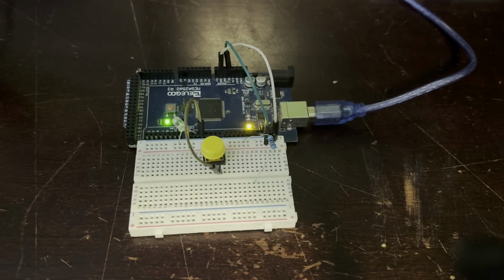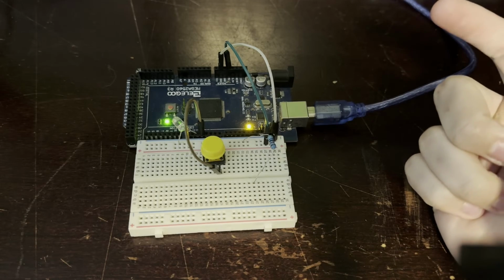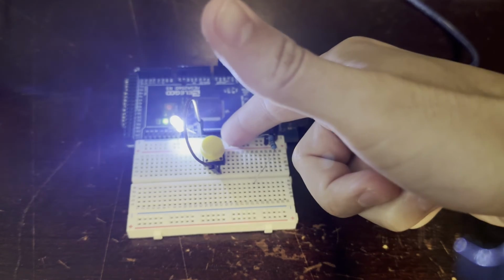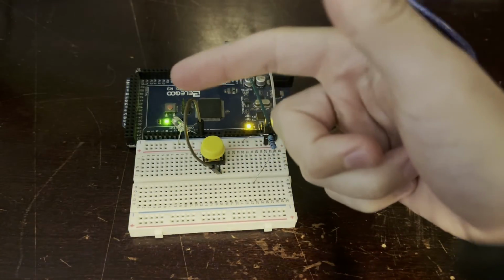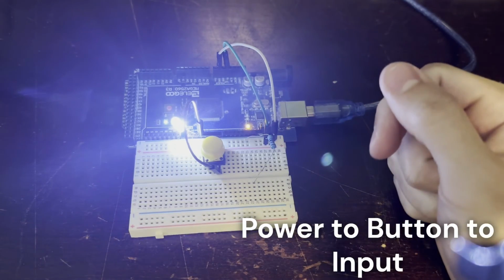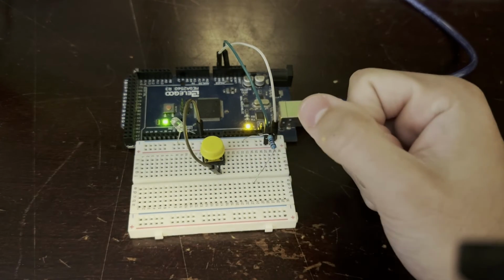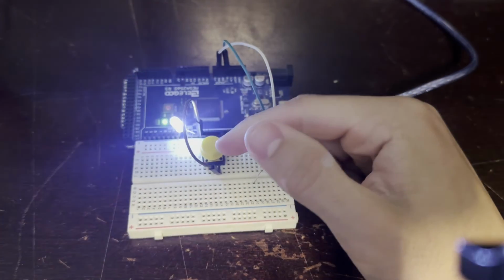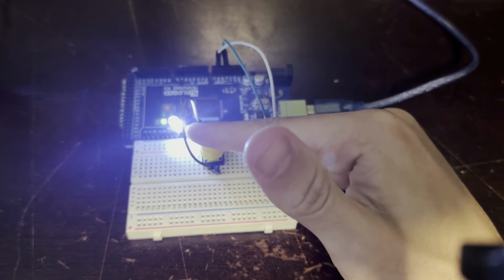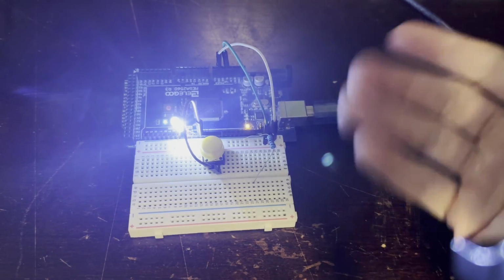Okay, so welcome to the little desk setup that we have here about floating points. Most people, whenever they start off with Arduino, wire up a button, connect it to the power, and then have a wire from the button to the digital input on the Arduino. But this is floating. So this is the floating point that we're talking about in the simulation right here. If the button is pressed, the light's supposed to turn on. But the light doesn't know if it's a 1 or a 0 because the input is floating.